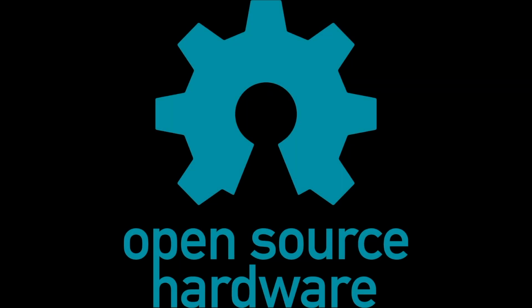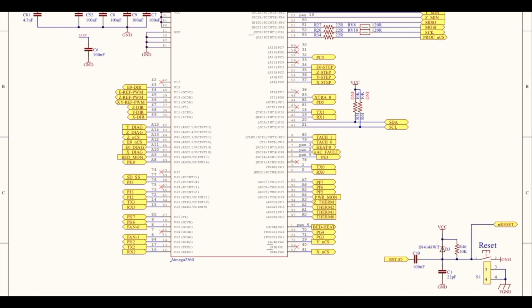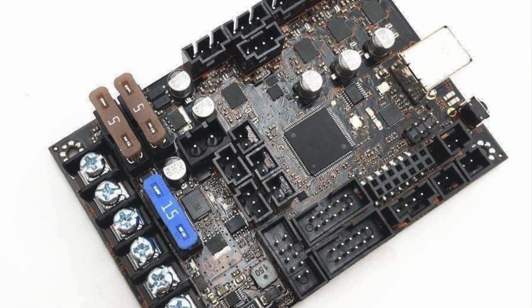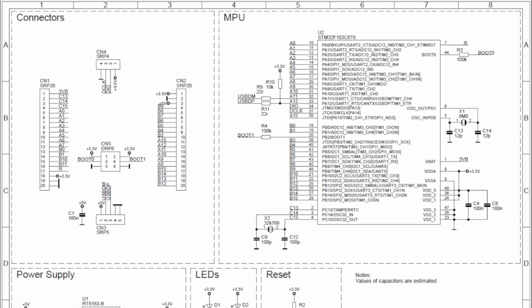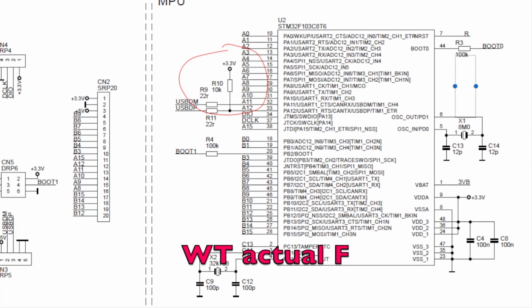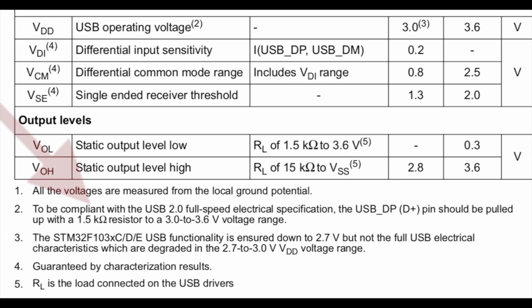Now, let's walk through the first steps of troubleshooting if we're talking about open source land. Pretty simple. Bring up the schematic files, see what the designs are, see where the pins are routed, and if that's all happy, compare it to the actual board hardware, and just check first for no-brainer problems. For example, if you have this schematic, you can look up here and see, hey, what the actual F is going on here. 10K pull-up? Are you serious? With 3.3 volts? Diagnosis? It's a design issue. Whoever made this board didn't read the datasheet all the way through.